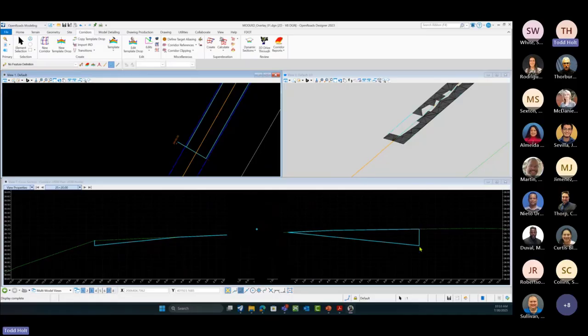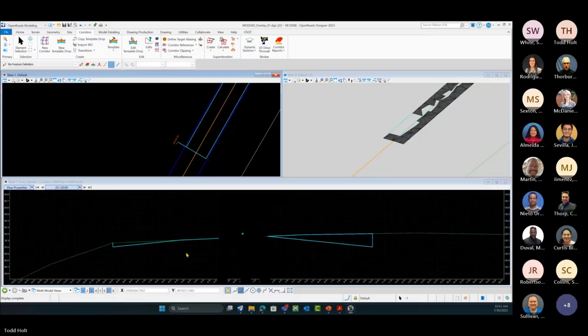We'd have to mill down to get that 2% slope that we're trying to create. And then we would have to fill that back in, or that would be the bottom to the design. So we're going to mill and then put back our pavement design, and it's following that 2% that we have here. Right, so those are our 2 different milling components. So that's really just building those two different ones that we have in there.